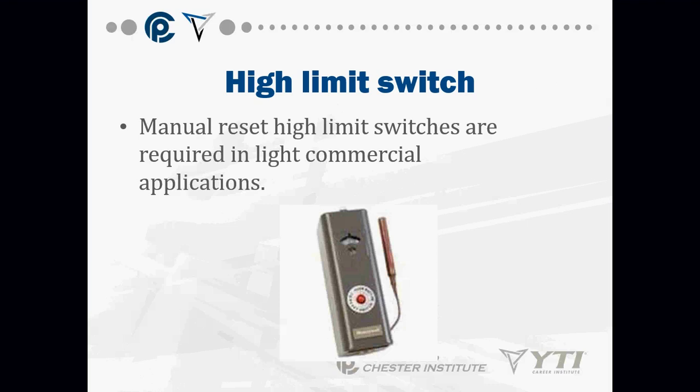In residential and light commercial, your high limit switch is most likely going to be simply sensing the boiler water temperature. Kind of similar to what the Aquastat is doing, but it'll probably be located somewhere further down the line a little bit. If you're dealing with industrial and heavy commercial type boilers, you will probably have a high limit switch that's also going to sense the temperature of the combustion chamber, kind of similar to what a forced air furnace is. Almost the same thing.